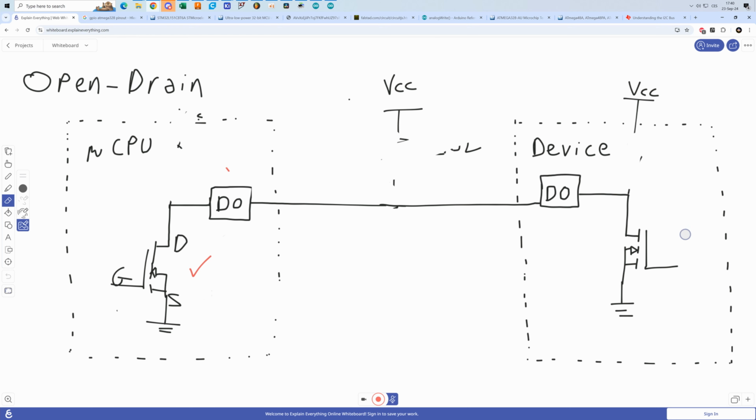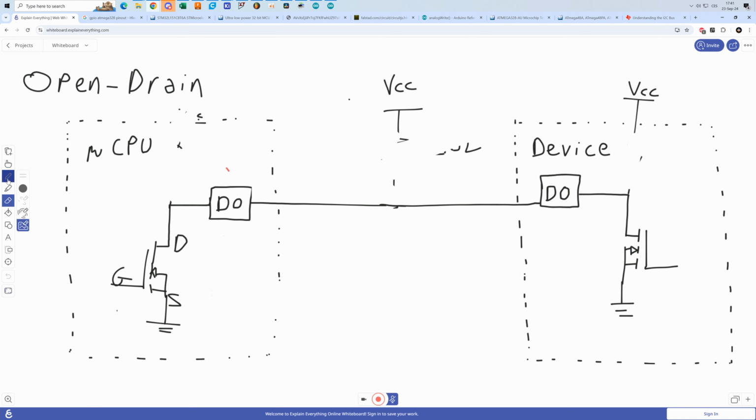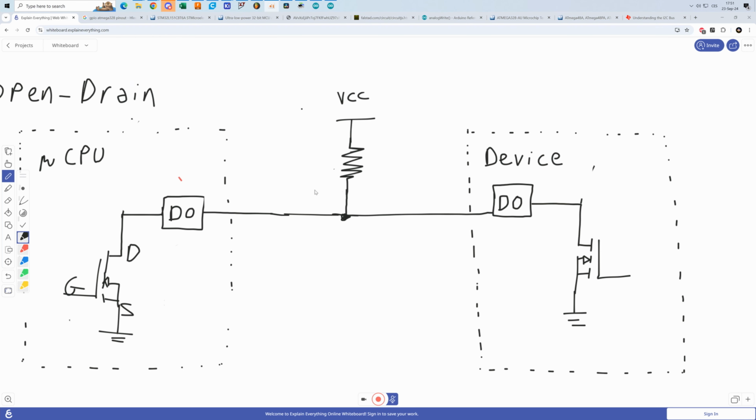So we have open drain configuration. And every time the data is high, well, then actually no transistors are conducting. It's actually the resistor, which we had over here, that is dictating the state of the bus. No transistor is turned on. This resistor over here is actually, in most cases, the limiting factor to the speed at which our bus can transmit data. Why is that?